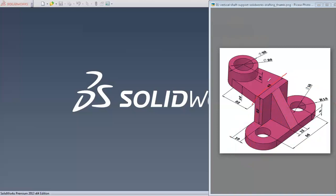Now for this part, I do know that this line is making a tangent on this. So to get this tangent, first of all, I have to make this cylinder or at least a circle. So I will first draw this circle at 32 mm distance from here, which will be at the middle of this section. Once I draw this circle and create this cylinder, then I will create this cross section area. So this will be our last part, right? Then I will change the color. So this is the idea of drawing this one.